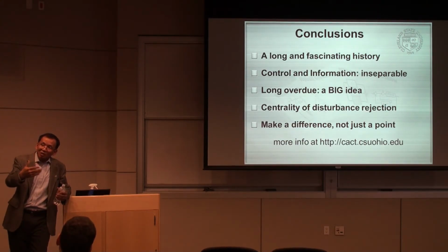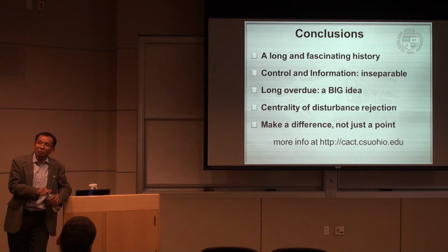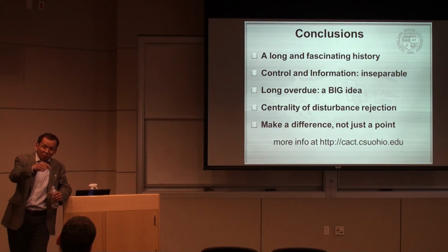Taking advantage of our knowledge of the plant helps us reduce the bandwidth of the observer. In one case, in MEMS, we applied this to a MEMS gyroscope by incorporating the omega squared y and the damping term into the observer. We were able to reduce the bandwidth by three orders of magnitude. So that worked out very well.